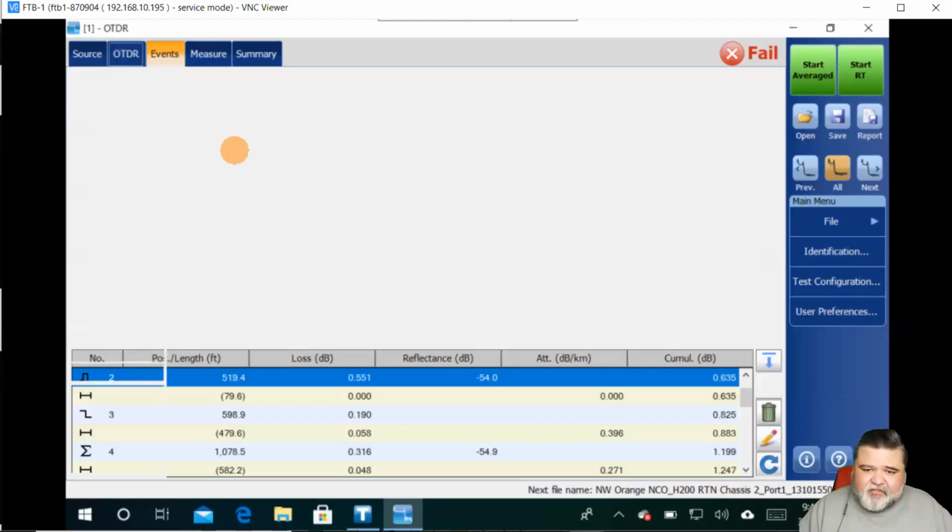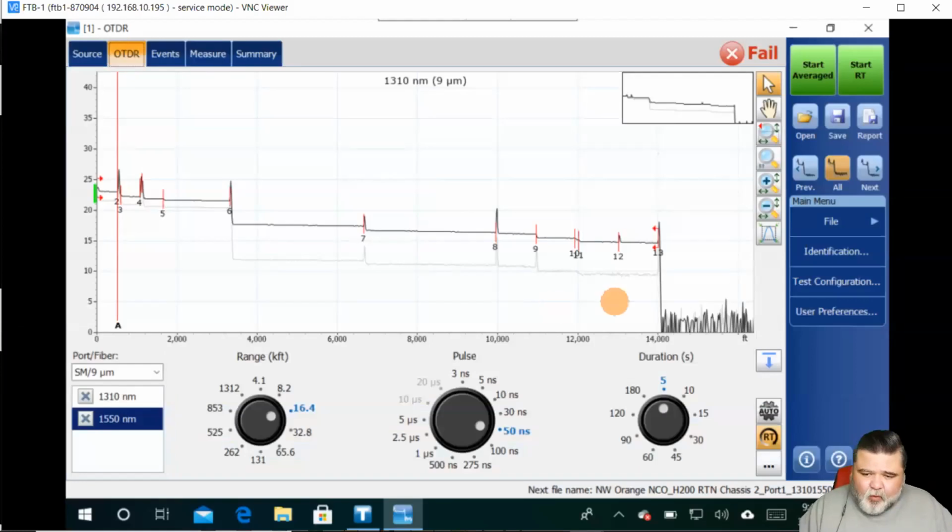And so to kind of summarize some of the stuff that I talked about, when it comes to an OTDR, it's important to understand the critical parameters and the pass-fail thresholds of all the different components you're looking at. What is my splice loss? What's the difference between my unidirectional splice loss and my bidirectional splice loss?